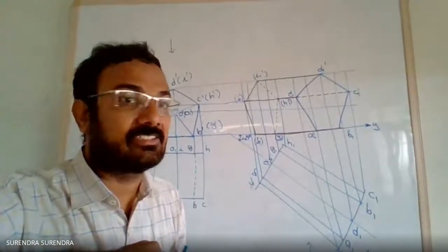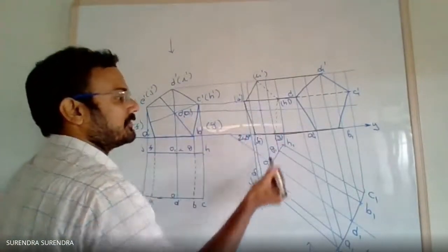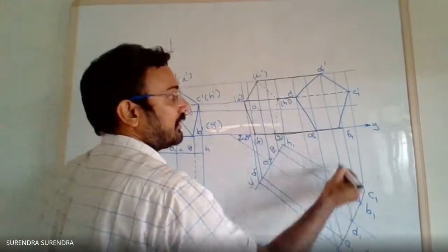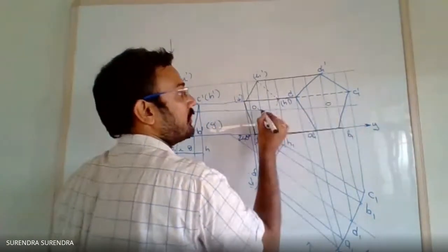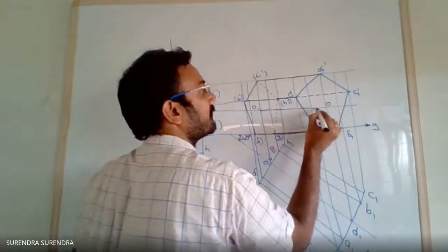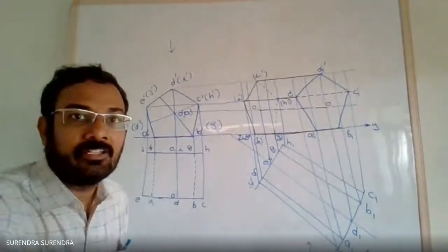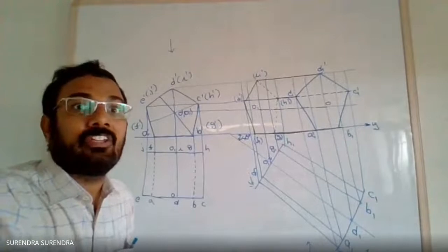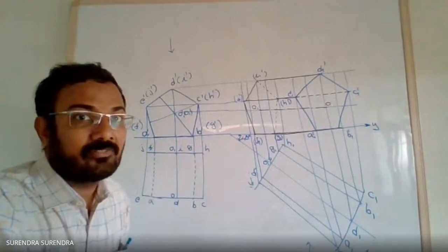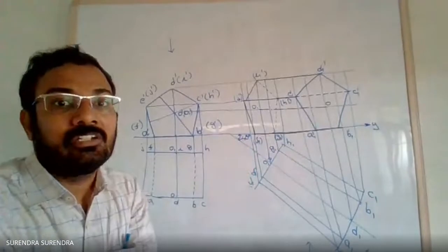One more thing is the axis. Projection from O, this is the point O1 and O. Join this as an axis line. So with this we completed the position of the prism when the axis is inclined to the vertical plane at 40 degrees and resting on one of its rectangular faces on the ground.